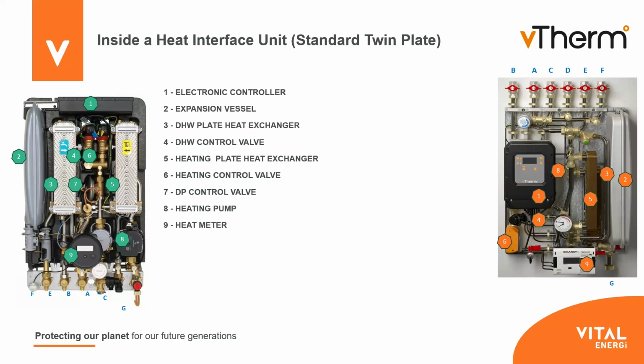This is therefore to give you your kilowatt output and other information, maybe temperatures. That could be interrogated by a third-party product, or in our case, we also use our own in-house product, the glass, as I've mentioned before, and therefore you can get all your metering information and also help with billing as well. Your pressure relief valve. So again, if the heating circuit goes above 2.5, 3 bar, that pressure relief valve will then release.